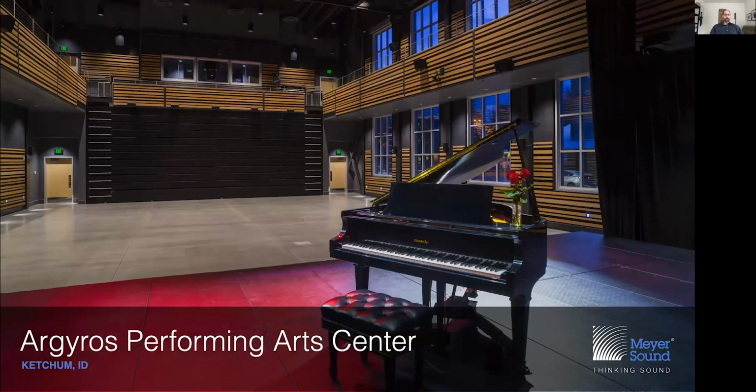So here we see a photo of the seats that are retracted. What happens when you retract seats like that is it removes all that absorption that the seats are providing, and it's also exposing the concrete floor. So now you went from a room with a low reverberation time to a slightly longer reverberation time. So what we typically do is create different presets for the different room configurations, which is what we did here.